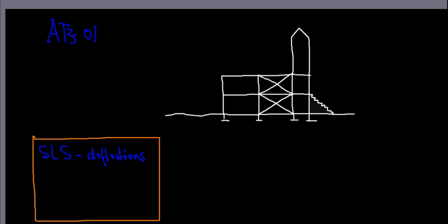Let's do an example on what deflections means. Say we were to pick a certain slab here, which I'm circling in red, and I, for a second, create a so-called structural system. So instead of drawing this column here or these other three columns, I basically say I'm just looking at that slab and I give little supports where these columns hit the slab from the underside.